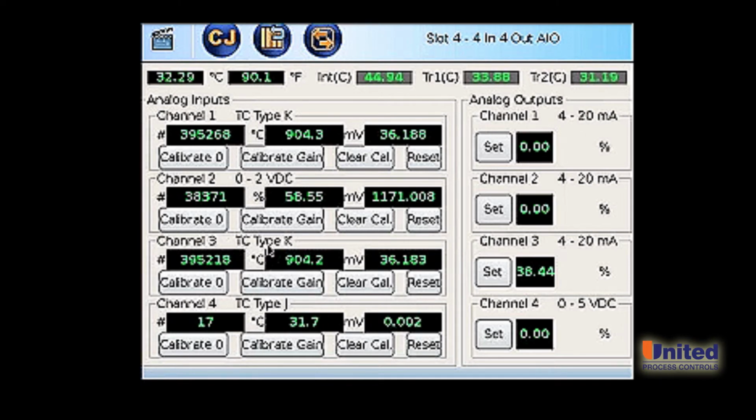Even though each one of these channels is showing the designation or thermocouple type, the calibration at this level is strictly linear and only requires a 0 to 96 millivolt signal with copper wire. Thermocouple TC extension wire is not required at this point in the calibration.